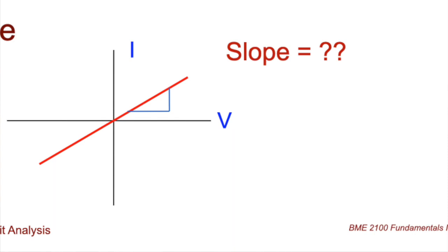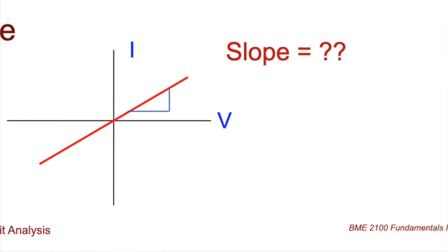So we can adjust the voltage, different values, record the associated current. In this case, we have both positive and negative values. Voltage can change polarity, and with that, the current direction will also change. But we get a straight line. And we also know, what do we care about when we have a straight line? We care about the slope, and we care about the intercept. So in this simple circuit, the intercept goes through 0, and the slope is what? Well, the slope is current over voltage. And current over voltage is the same as conductance, G, 1 over resistance. This is just like what we saw in this situation with flow. Should feel familiar. And if it doesn't, go back and look at that other stuff, because you've got to know this.